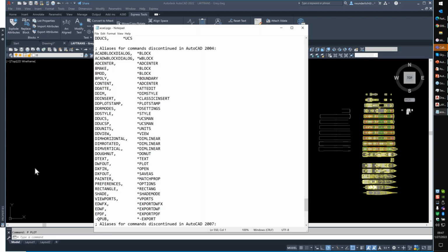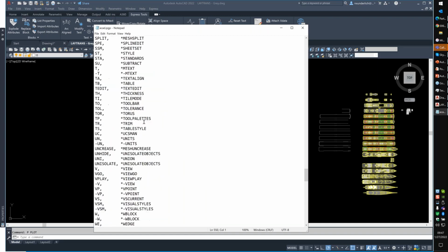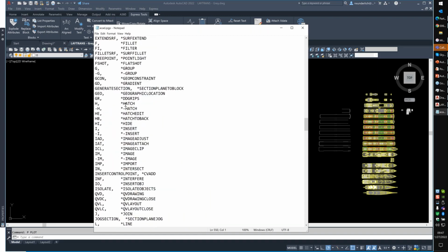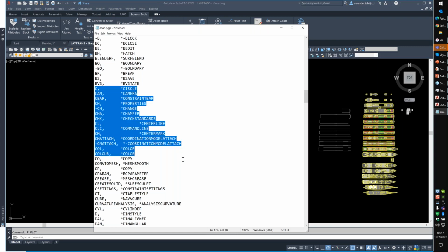If you change C to copy, do you need to provide a new keyboard input for circle? I generally recommend doing something for circle because up in here, you'll find that C is defined as circle, but C is not defined anywhere else. That's why I always define CI for circle, because that's what it was for me for many years. And I believe it was 2005, 6, 7, or 8, somewhere in there, that Autodesk changed the PGP to be different from what it's been for years.